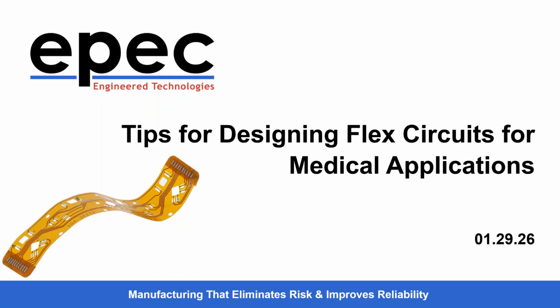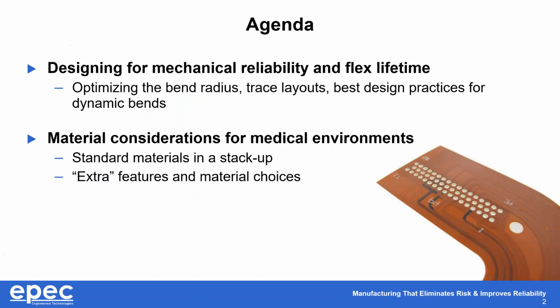So just as he said, we're going to be covering different tips for designing medical application-based flex circuits. During this presentation, we'll be addressing mechanical reliability and flex lifetime, touching on key aspects of those like bend radius, trace layouts, and different best design practices for dynamic bends.